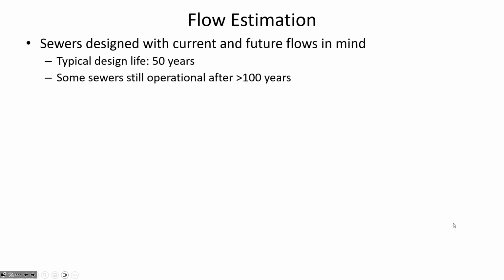It's hard to overestimate how long sewers may be put into service. There are plenty of sewers in the area here that are well over 50 years old, and a lot of communities in the United States where the sewers are more than 100 years old. And so if this infrastructure is going to be in place for that long, you have to be very careful in thinking about what the future conditions will be and sizing the pipe for the flows that you expect in the future. So if you're in an area that's already pretty well established and built up, then maybe your current day flows are a good estimate for what you'll have in the future.